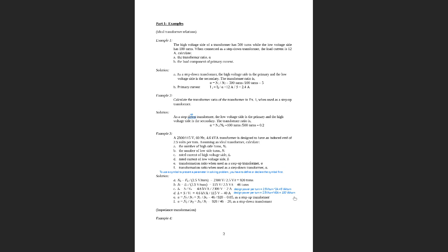So in practice, the wires used for the high voltage side, which has many turns, and the wire used for the secondary side, which has fewer turns, usually have different cross-sectional areas. The per-turn resistance on the low voltage side is much smaller than the per-turn resistance of the high voltage side. On the high voltage side the current is smaller; on the low voltage side the current is bigger. So the heating effect is obvious. We have to reduce the resistance per turn on the low voltage side, so that the copper losses on the low voltage side are not so much bigger than on the primary side.